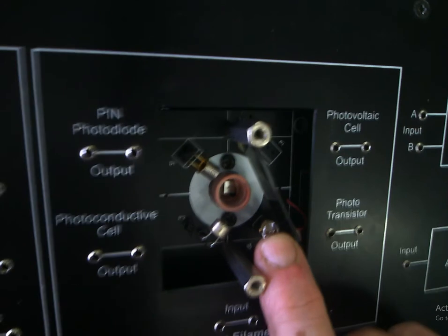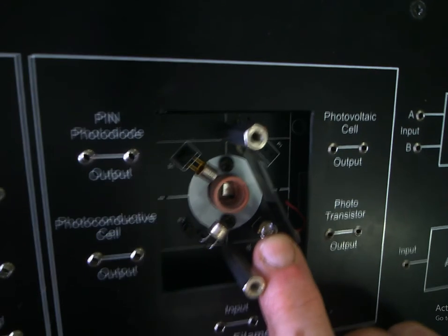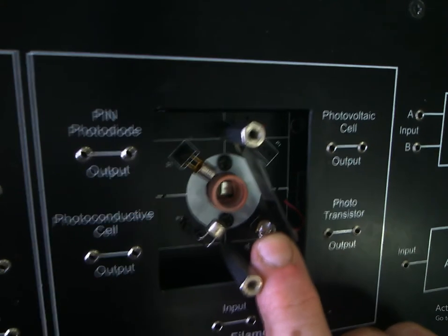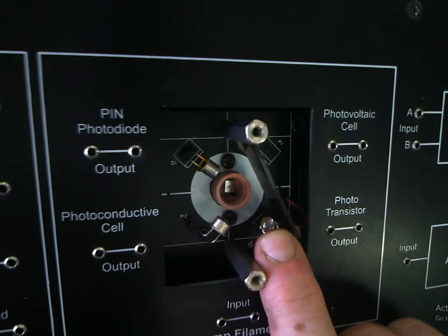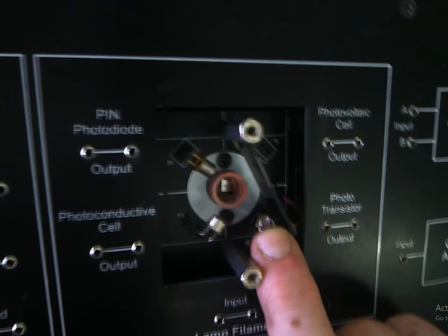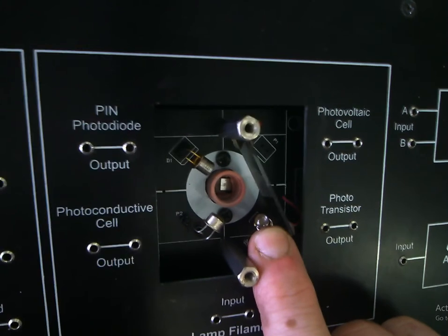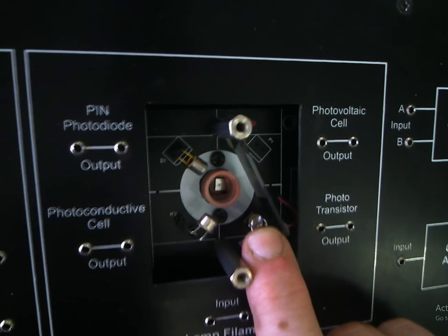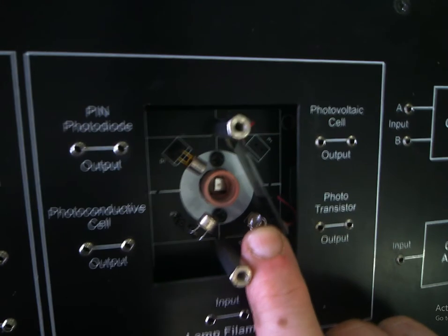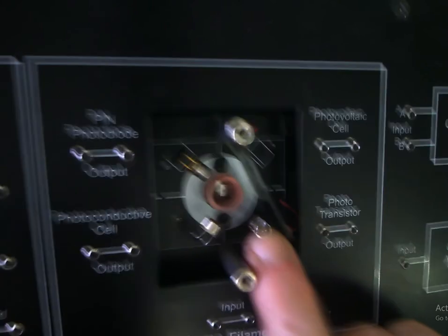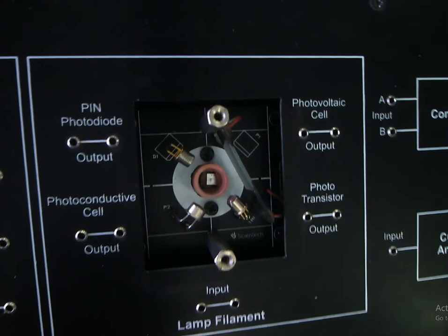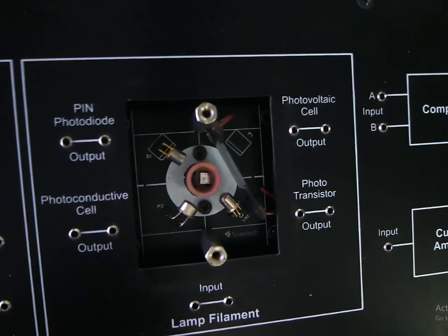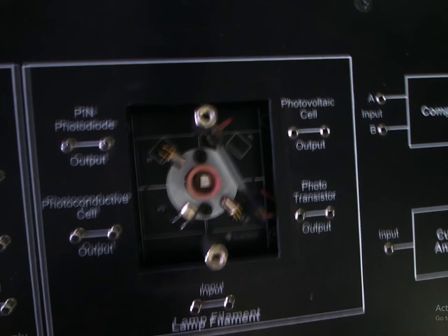And whenever the intensity of light is increased, current from collector to emitter increases if the transistor is properly biased. That means here intensity of light plays the role of base current. So when the intensity of light increases, base current increases, and definitely your collector to emitter current is increased.